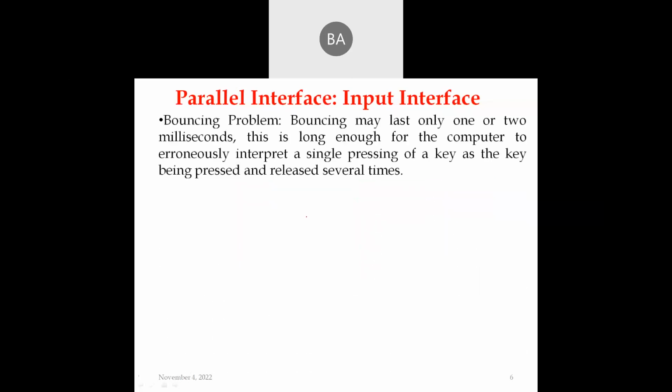Fine. Now there is one important problem that can be identified when we are inputting the data, and that is the bouncing problem. The bouncing may last only 1 or 2 milliseconds.